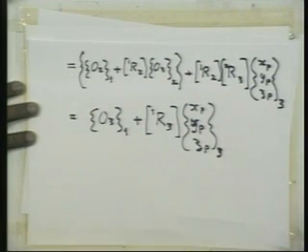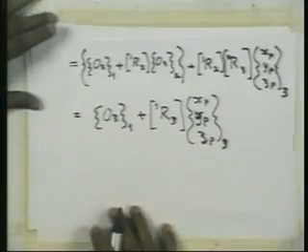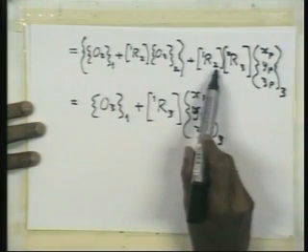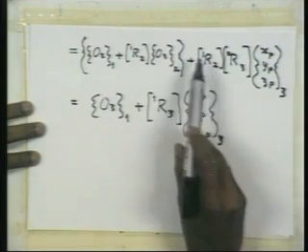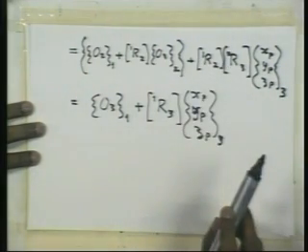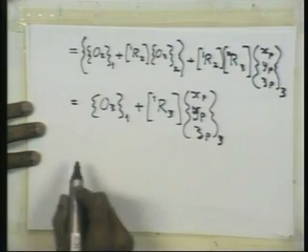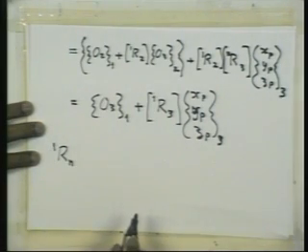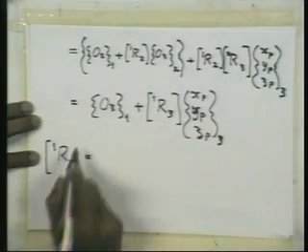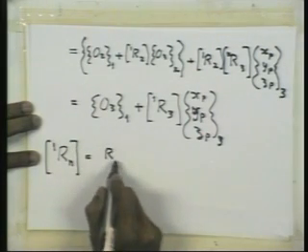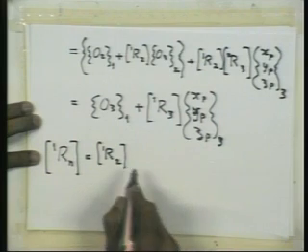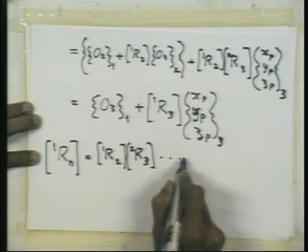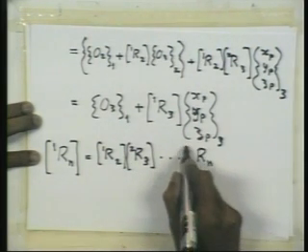fine. So one thing that emerges from here is the following thing, that is rotation matrix of 3 with respect to 1 is obtained out of multiplication of these two orientation matrices, 2 with respect to 1 post multiplied by 3 with respect to 2, and I can generalize it and write R of some nth reference frame with respect to the first reference frame equals R of 2 with respect to 1, then R of 3 with respect to 2, and so on, and finally R of n with respect to n minus 1.